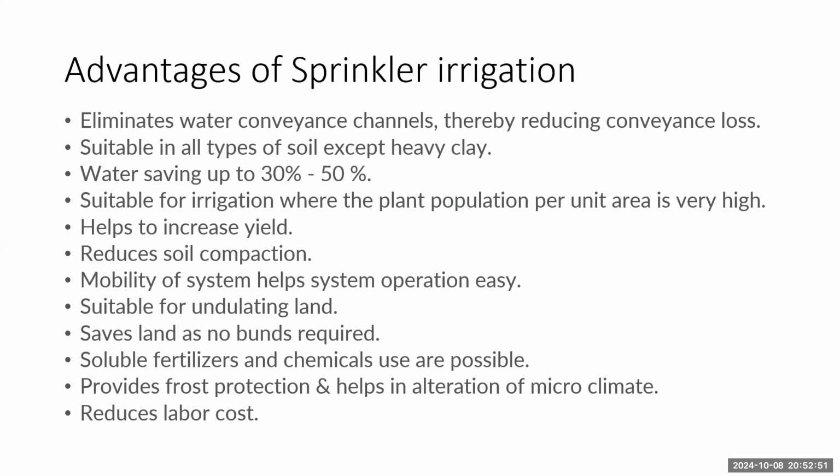We have seen figures in which the conveyance channels are in the form of a supply ditch, field channels, or drain channels. All these are called conveyance channels. Here there is no need for conveyance channels, so they are eliminated, and this reduces conveyance loss. What is conveyance loss? We have just discussed it: it is the loss of water during its journey due to percolation and evaporation.